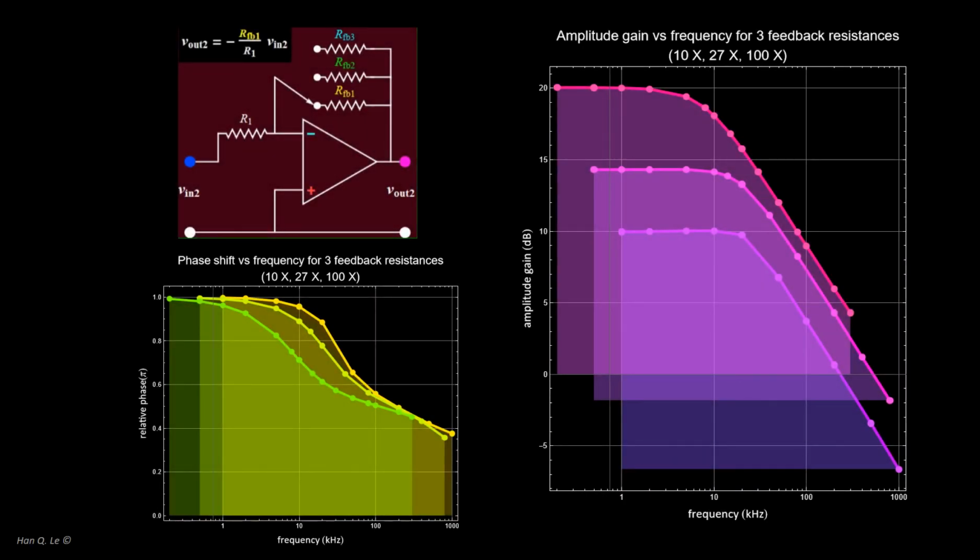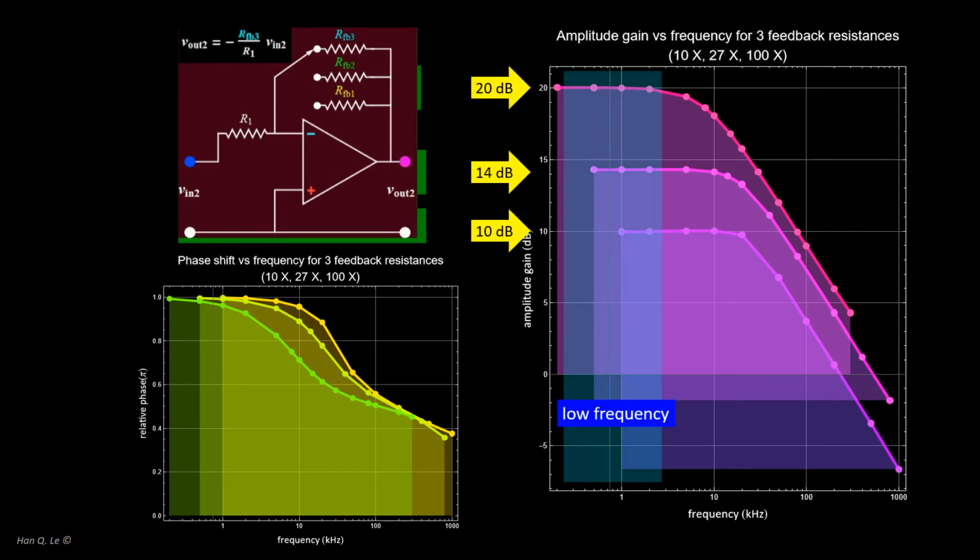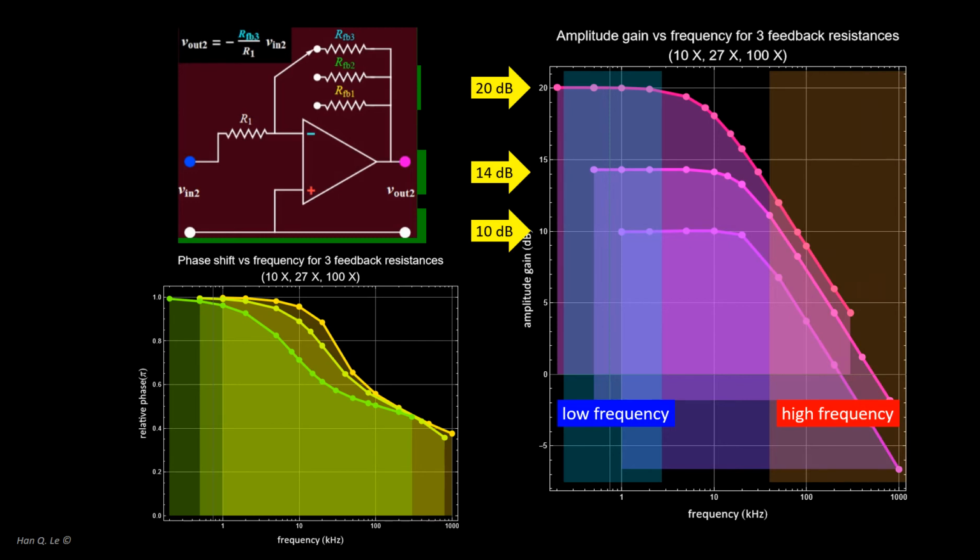The graphs shown here are the frequency, amplitude and phase responses, also called Bode plots, of the amplifier, as measured from step A5. The dots are experimental data, the lines are linear interpolation connecting the dots. On the amplitude response plot on the right, the amplitude gains obey the op-amp simple model at low frequencies, but clearly not at high frequencies.